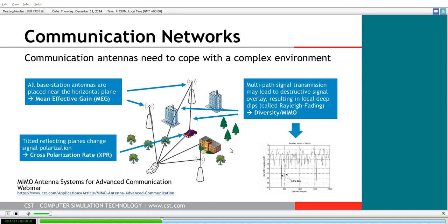Of course, that's just a path consideration, but there's also polarization decay rates as well that can individually be accounted for in models as well. The way to combat this type of fading that can occur, what's called multipath or Rayleigh fading from these multiple paths, is to introduce diversity into your antenna design. This is the so-called multiple input, multiple output antennas.